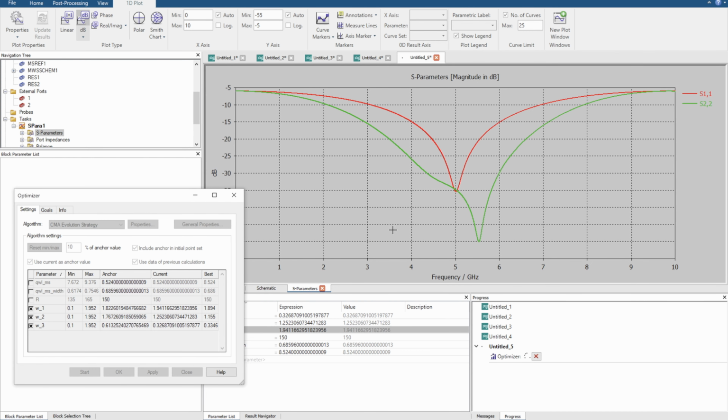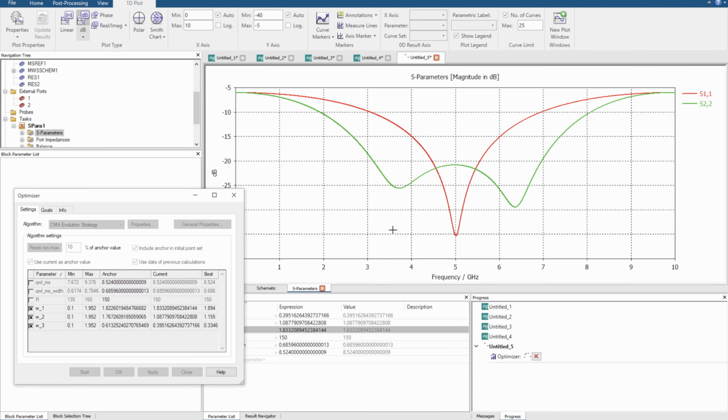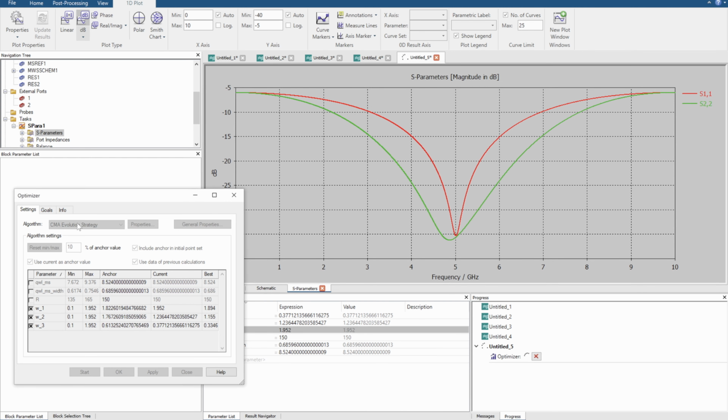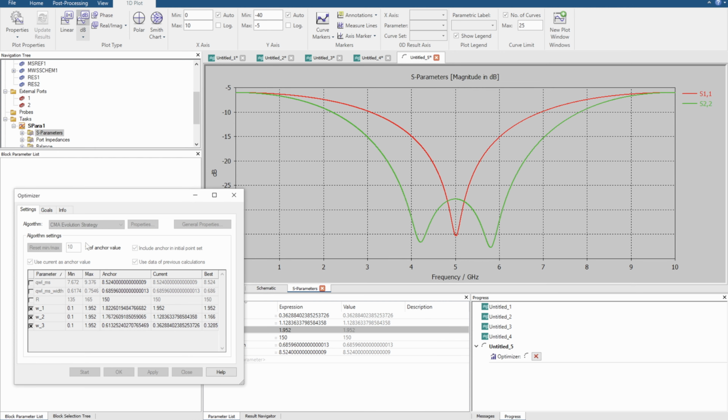So if you wanted that to be perfect, you would ask the optimizer then, once it's found a result, to have control of the individual quarter wavelength values, and then say you can only wiggle it just a tiny bit. And then you would ask it to use trust region method, and then it will slightly fine tune.